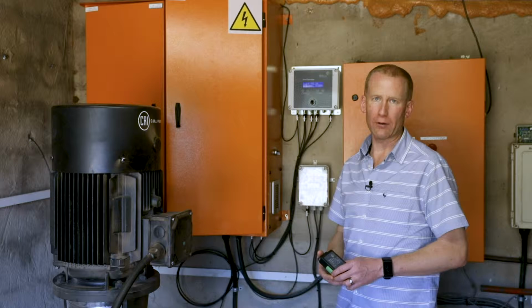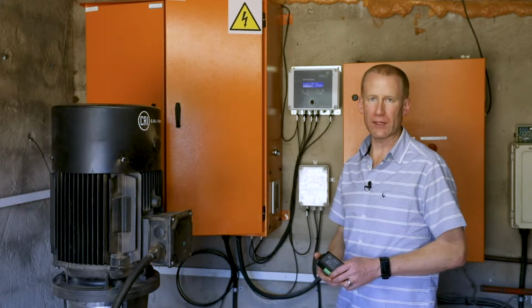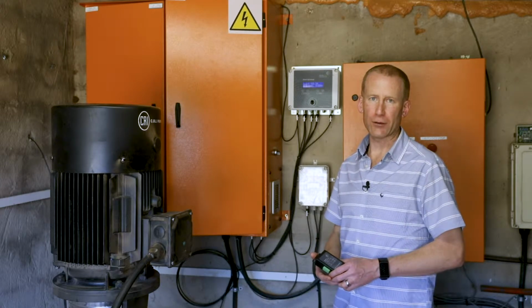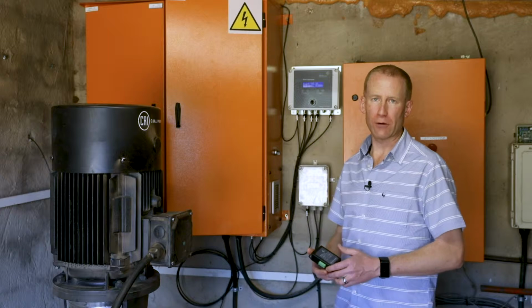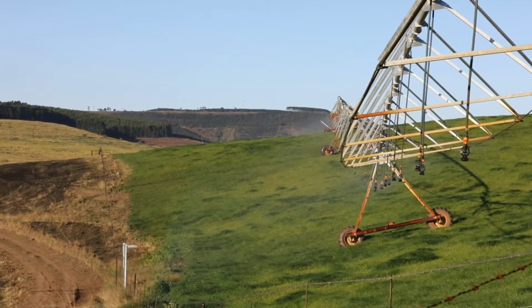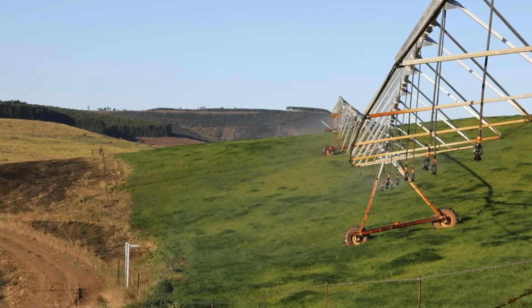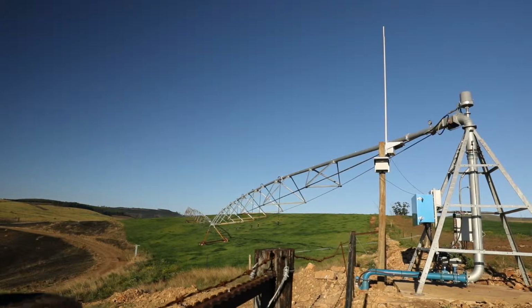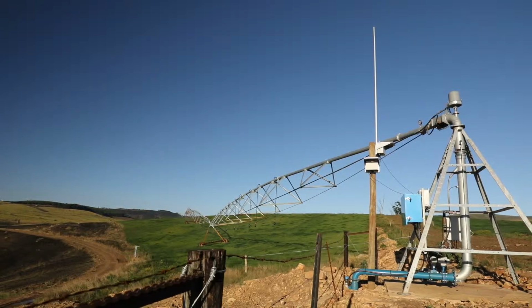If the pressures are below the set points, it increases the speed of the pump. If the pressures are above the set points, it slows down the speed of the pump. The objective is to make sure that one of the pressures is at the set point while the other pressure is above the set point. So for example, if the pivot is facing uphill, the lowest pressure will be at the end of the pivot, so the system will control the end pressure. When the pivot is facing downhill, the lowest pressure will be at the center of the pivot, so the system controls the pivot center pressure.